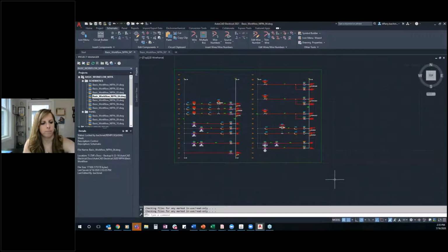All right, and we have what looks to be a Vault question. Following the electromechanical workflow, saving or working from Vault, my first project went fine. My second project, when using the same components, raised a red flag upon saving to Vault due to a component with the same file name. Okay, so duplicates basically. Electrical uses the same file names. Yeah, Inventor and actually there are some applications that are going to have files with the same name.